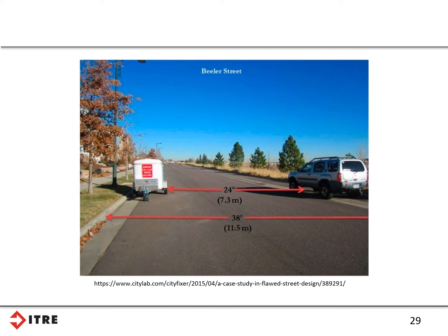And so the thought is, what if we add in our own kind of choker element here to reduce the width of the roadway to 24 feet, which is still two 12-foot lanes, so still plenty of room for mobility there, but just squeezing in the traffic a little bit, creating a little bit of friction to try to reduce the speeds on this roadway. And so this concept can be implemented very simply, very quickly, just to test and see what the effect is. Maybe even testing how frequently you need these slow points before putting in something more permanent with concrete or other materials.